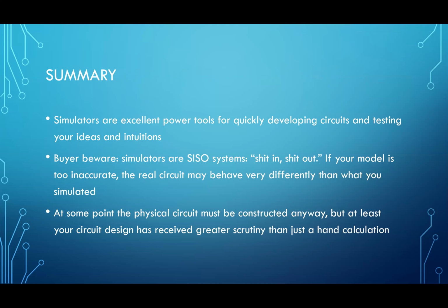But I would say probably about 95% of the time, even if you're an experienced circuit designer, there's going to be something that you didn't anticipate, that you just did not think through, especially for circuits that have lots of nonlinear behavior, things like switching circuits, say a motor driver, where some transistors turn on and the other transistors turn off, and you're trying to figure out the sequence of events. There's just all sorts of behavior that is not very intuitive. And even if you have an intuition, it may not be perfect. So about 95% of the time, you just don't get it right. And so it's very useful to run a simulation to at the very least prove out your idea before you build the thing, and that can save you a lot of time and help you figure out if your idea is problematic, how it's problematic, and how to fix it.